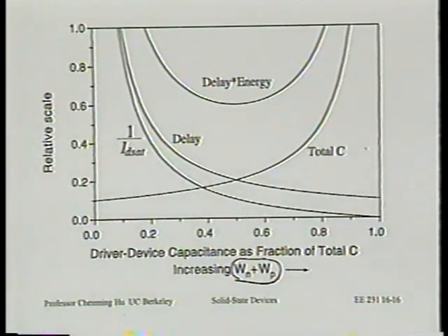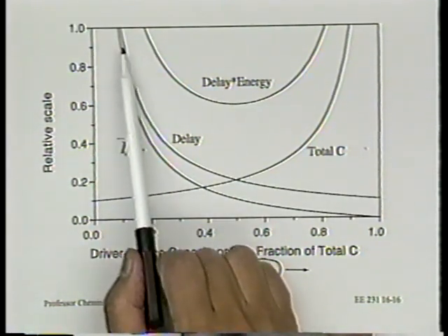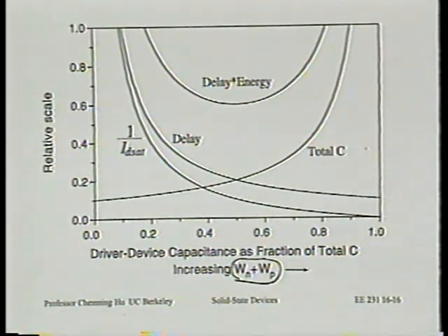All right, ratio is one thing. We're already settled on that. It could be 1.5, could be 2, right? Then how large a W should we use? Well, it turns out using the equations that we introduced last time, using differentiation to try to minimize things, or in this case we don't even have to minimize anything, I'm just plotting it. You can show that the delay time decreases monotonically with increasing W. In other words, using larger W always helps.